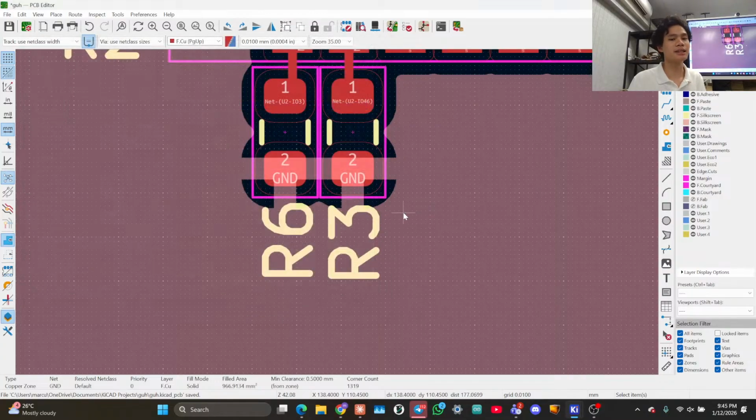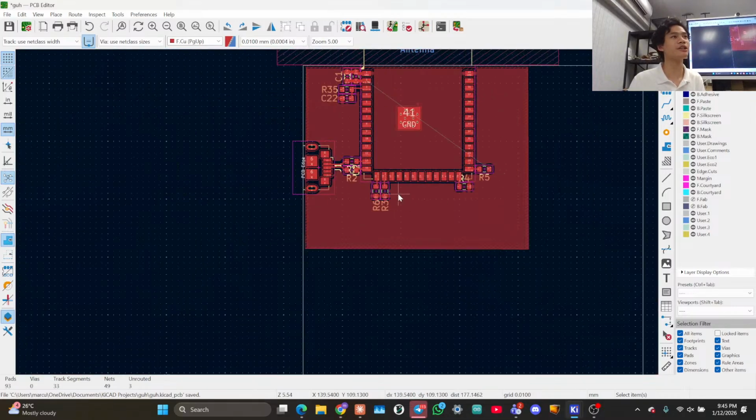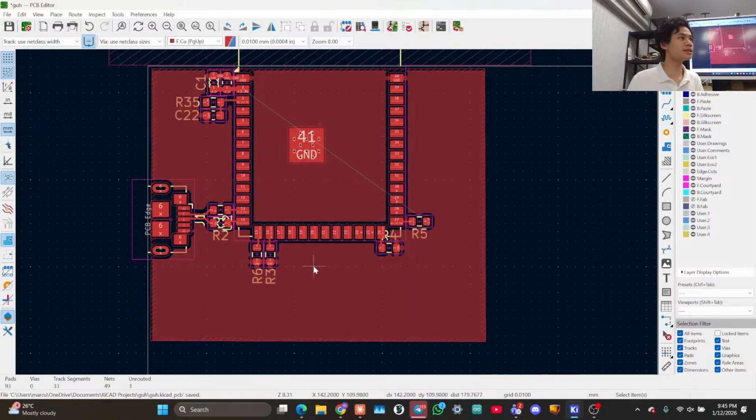What that does is we don't have too strong of a copper connection, because if the copper connection is too good, then this will act like a heat sink, and when we try to solder this, all the heat will fly away from the pad and we can't solder anything. It will just dissipate into this giant copper area. This is a thermal property of the board, and thermal management is the thing we'll talk about next lesson. For now, just know that things get hot, and sometimes things are supposed to be hot.